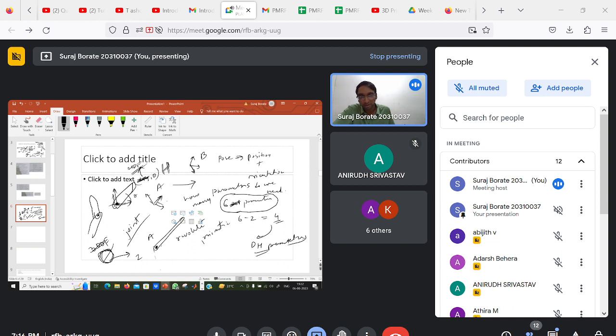Complex joints can always be represented by simpler models. So this is what can be done if that question comes to your mind, like in case we have complex joints, not revolute and prismatic, then how many DH parameters will there be? In such a case, we say that there are two revolute joints over there, and the distance between them is 0, something like that.